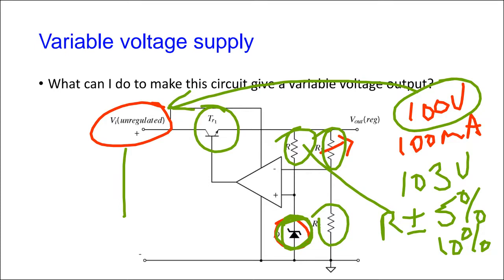characteristic is supposed to do this. That variation there happens, it is not perfect. There's a little bit of variation and it depends on the current through the Zener. So one way to insulate that, instead of supplying the Zener with a resistor, we supply the Zener with a fixed current, a constant current, right?